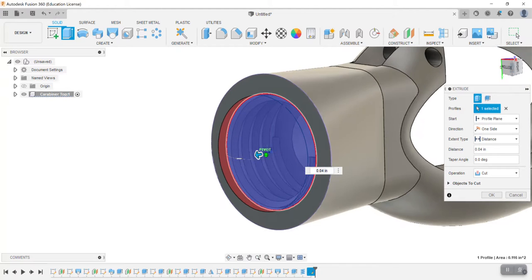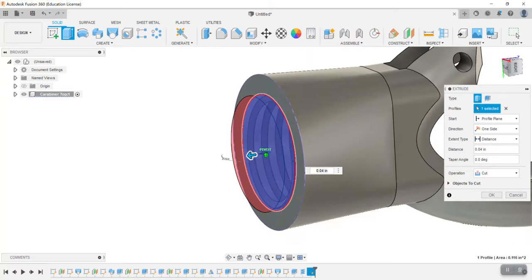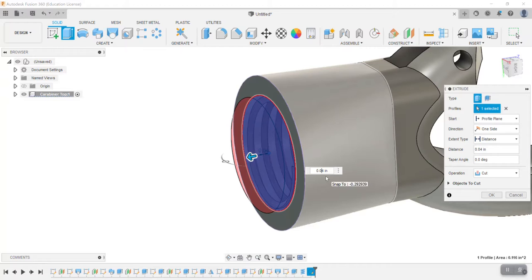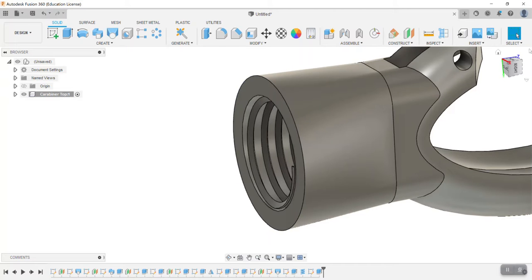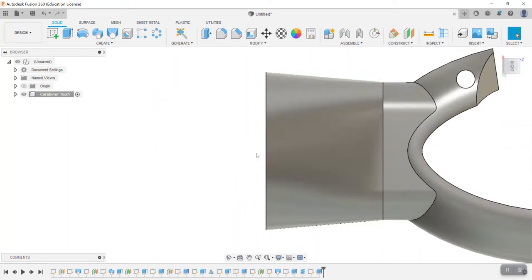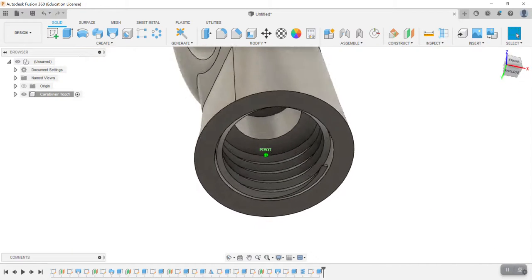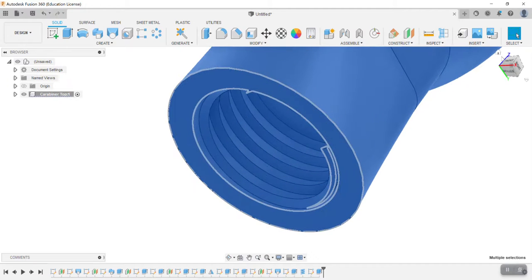It seems like we're kind of cutting into open air, but what that does, if I cut that to a distance of 0.15 inches, let's say, just so we can make sure we get plenty of the effect, that will make sure that whatever we have left, when I turn to the side, I've got a flat portion there on the bottom. So there's where the threading will kind of go through and stop on that.